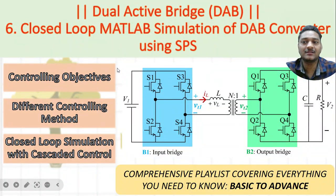Now in this video we are going to understand how to implement the closed loop MATLAB simulation. First, you need to understand what my controlling objective is. When we did it in open loop, my controlling objective was that my output V0 should be constant. In closed loop simulation with single phase shift, my controlling objective will remain the same: V0 should be constant. But with double phase shift or triple phase shift, the controlling objective should change, or should be more than one. What those are, we will see.